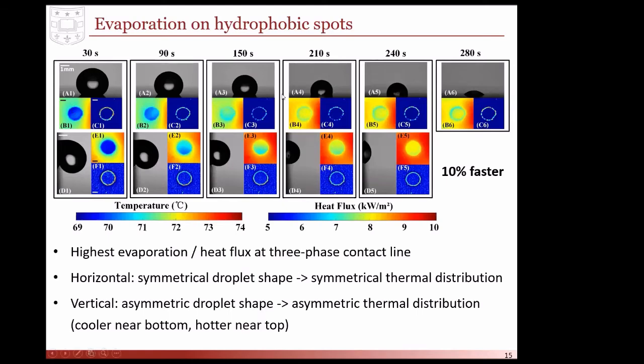So if we look just at a regular droplet on a horizontal surface, because we have a superhydrophobic matrix, but pinning at the basically transition area between the two wettability patterns, we start with a droplet with a very high contact angle, and we end with a droplet with a very small contact angle, but the base area remains the same. So that allows us to really normalize the heat transfer rates that we're measuring.